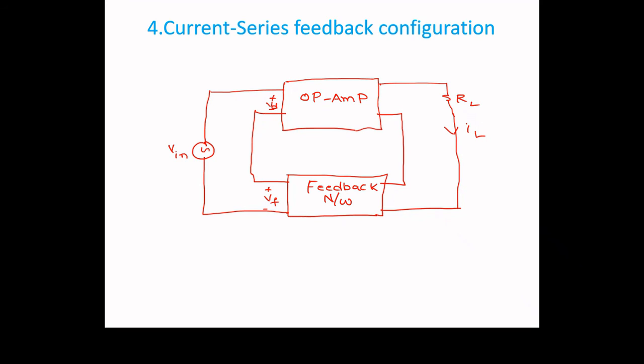So we have seen the op amp in open loop configuration and in closed loop configuration. In closed loop configuration also, you can operate the device in differential amplifier mode, inverting amplifier mode, and non-inverting amplifier mode. Whereas in open loop configuration also we can operate the device in differential amplifier mode, inverting amplifier mode and non-inverting amplifier mode.